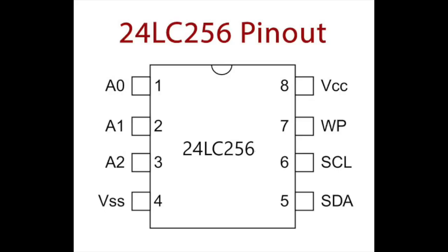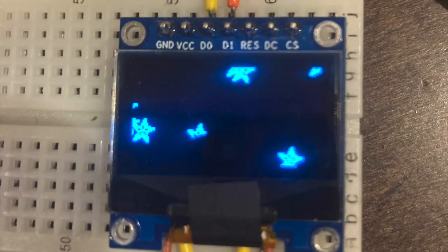Following that, the 24LC256 EEPROMs are the next pieces added to the circuit. These components store data that is recorded from the TC74 temperature sensor and the timestamp alongside it, and is drawn upon when asked for history by the HID controls added in a later phase. Up to 8 EEPROMs can be used on a single circuit, as the address used for the I2C bus can be modified. The modifications occur within the pins A0, A1, and A2, dependent on whether they're wired to power or ground. Then the OLED graphic LED display is added.